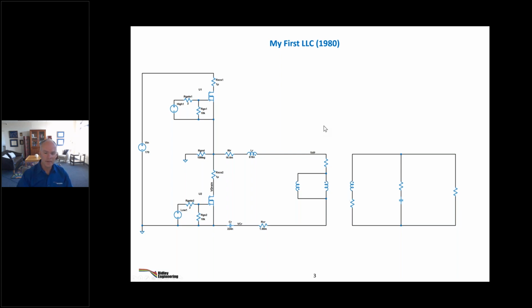And the other complication in this circuit was that the magnetics were designed to saturate. So during the resonance cycle, one of the magnetic elements would go into saturation. And the point of this was to create a ferroresonance circuit running at 20 kilohertz that would automatically regulate the AC output.